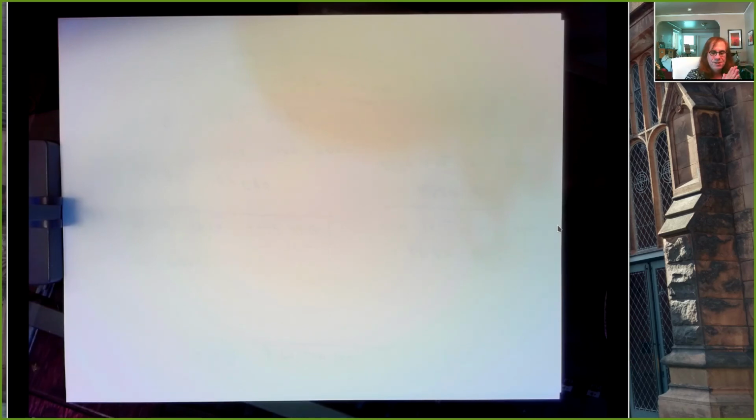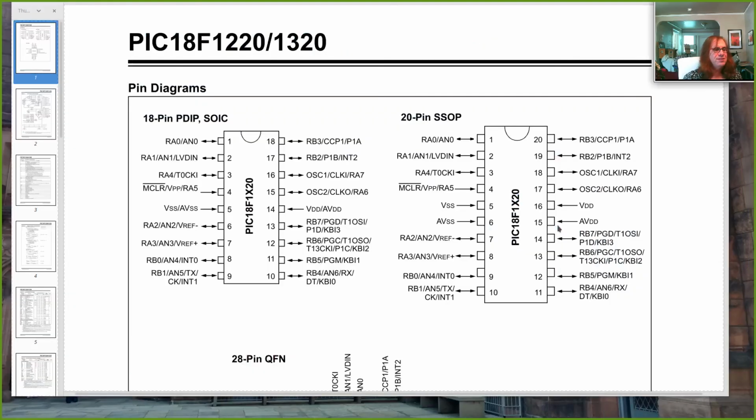And we'll set it to 1 if it's true and 0 if it's false. Our processors are byte-oriented, right? The PIC is basically an 8-bit processor. Most things happen a byte at a time. But the granularity of these pins is really at the bit level. So here's a single pin. We can specify a single value called RA0, and we can make it high or low, a 1 or a 0. Here's another pin, pin 2, which is connected to something called RA1. Pin 6 is connected to RA2 and so on.